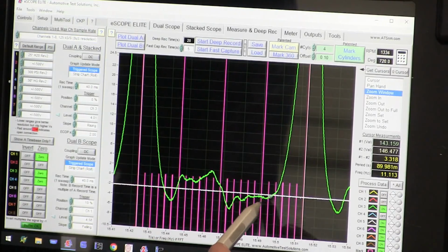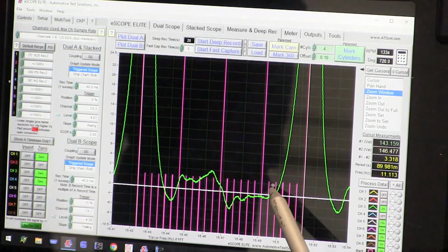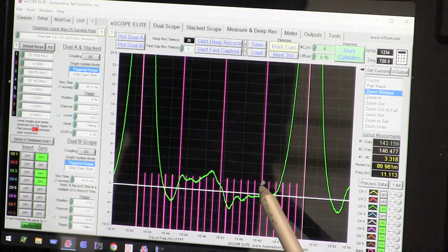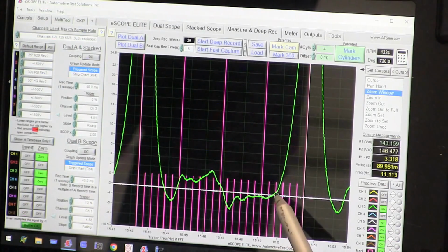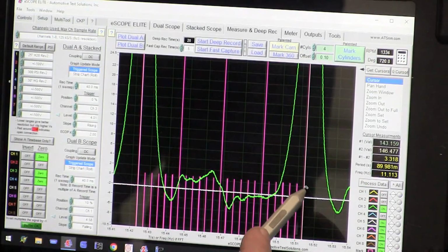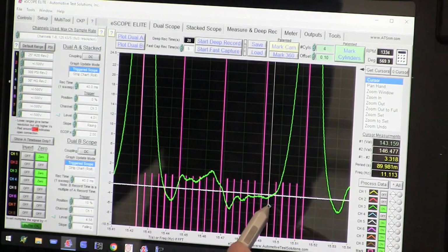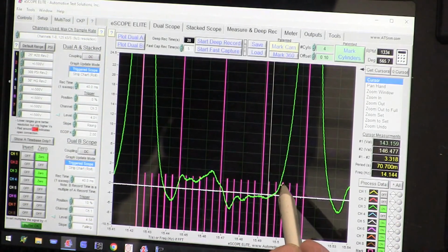But this intake is off. Do you see how this starts to rise right here at 30 degrees? So 30 degrees after bottom dead center right here, I'm rising. Well, that rise normally is way over here. It's past 60 on these engines that I've tested. Most of these engines are at about 70. So what that means is the rise is happening right here. I can start to see that rise right here.